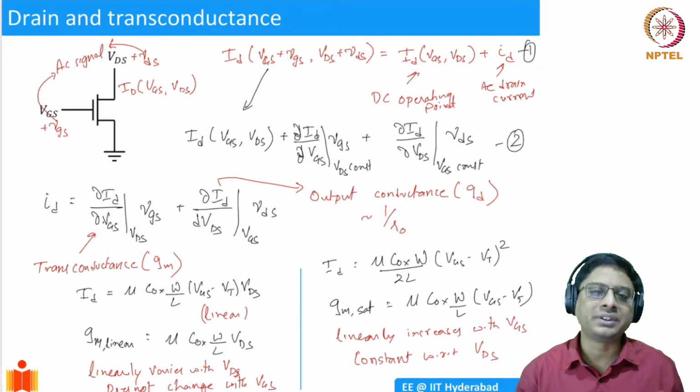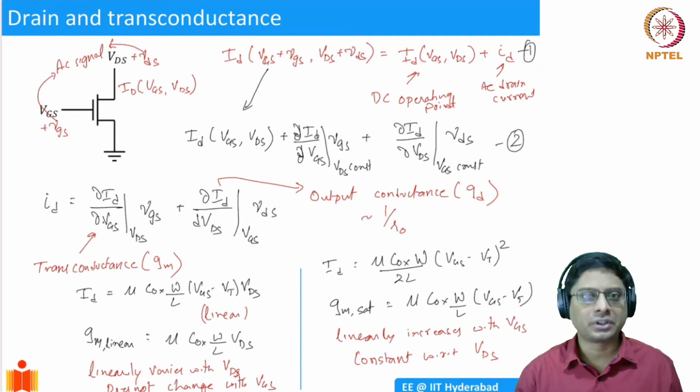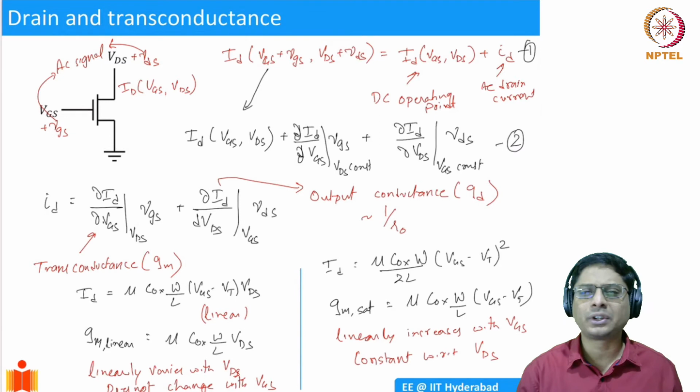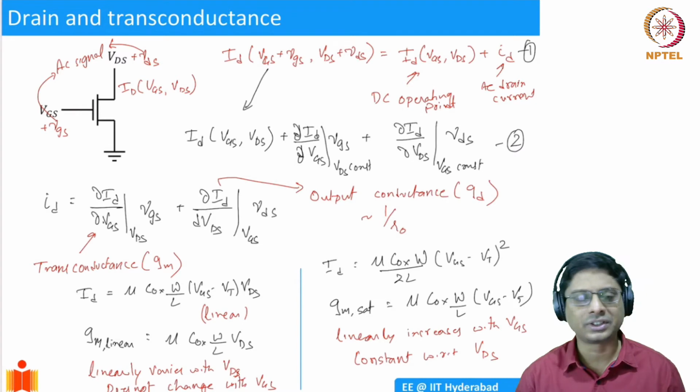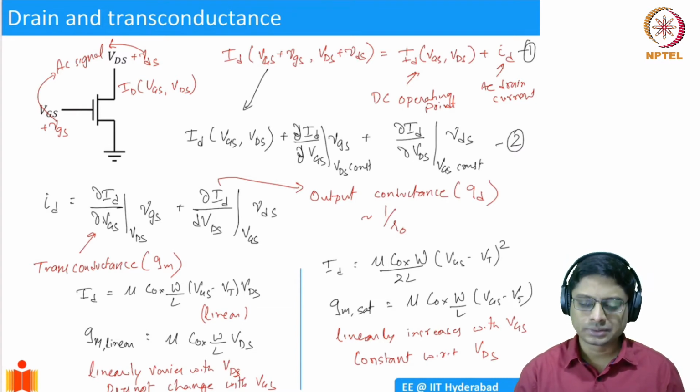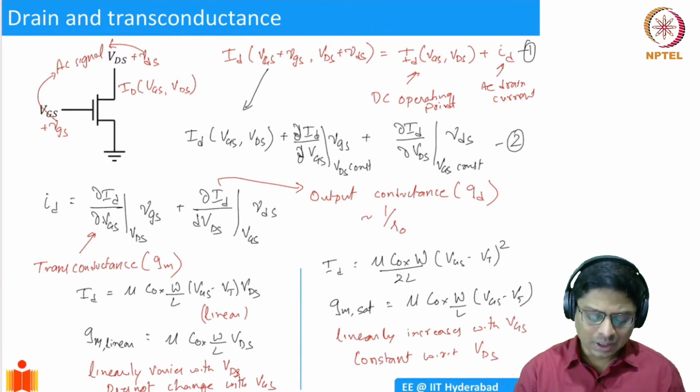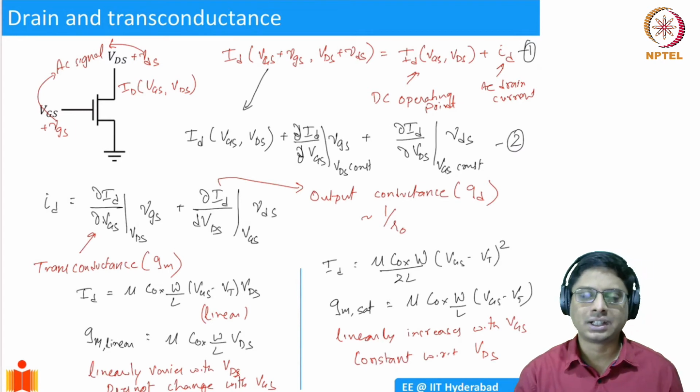But if you look inside an op amp, there will be a minimum of about 9 transistors, or it could go up to 27 transistors or so. You can actually have MOSFET circuits. You design the op amp, like the 741 that you use in your linear integrated circuits course, using design techniques like current mirrors and so on. That's a completely different specialized course that will follow this if you're interested. But that is in the domain of analog IC design.